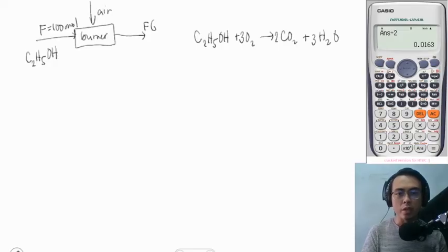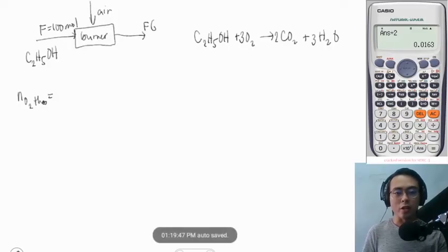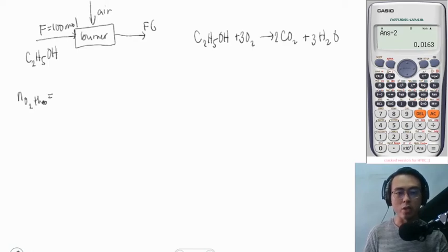Okay, so for this equation, we can solve for the O2 Theo. We just want to determine the O2 Theo for this illustration. So if you are given a particular fuel that you know the composition or you know its chemical formula, in this case, we know the chemical formula of ethanol, there is no modification to the way on how you obtain the O2 Theo. Okay? We still perform stoichiometry to determine how much oxygen we are going to need.